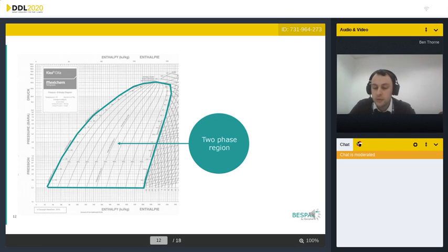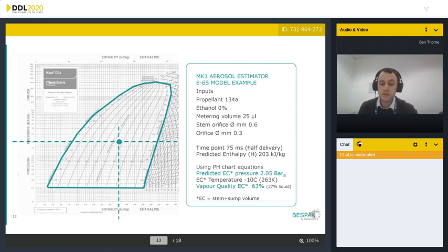And we can represent that process by a number of typically quartic polynomials. And we can calculate the properties we want using an iterative method if the other properties are known as well. So just as an example, we can calculate the enthalpy at each microsecond time step using a mass and energy balance as before, and we can iterate to calculate temperature, pressure, and the vapor fraction.